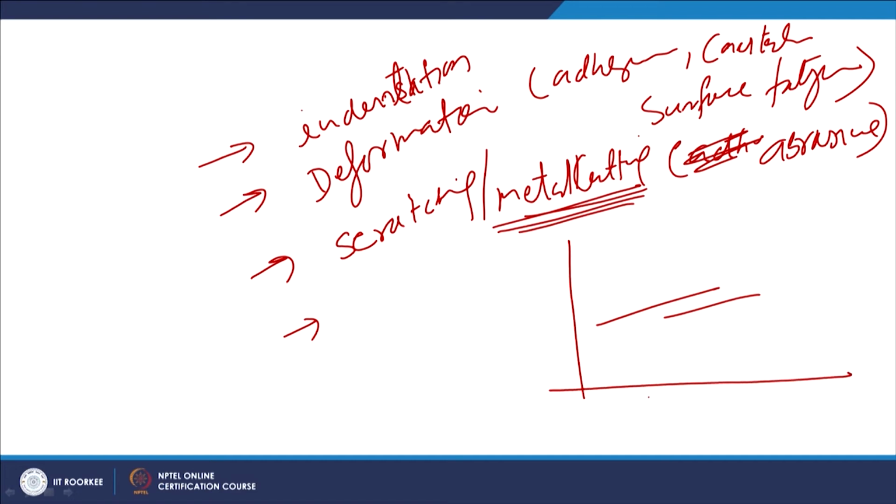When the abrasive hardness is far greater than the surface of the workpiece, the abrasive hardness does not matter, but when the hardness of the workpiece surface is greater than or close to the hardness of the abrasive, then the wear rate is significantly reduced.